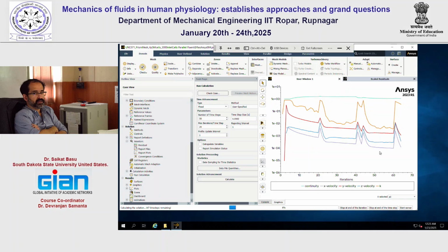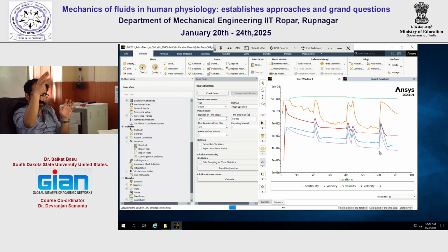We can do that. But the thing is, once the inhalation phase is done, the way the particle is coupled with the flow, we are trying to get the drag force, right? So the flow goes up and goes down. We cannot use the field when it goes down. We have to use the field in the mean region. So that's why we are taking this value once the flow is well developed. But you are trying to simulate the whole inspiratory phase. That has its importance, maybe for heat transfer, but not for particle transport.